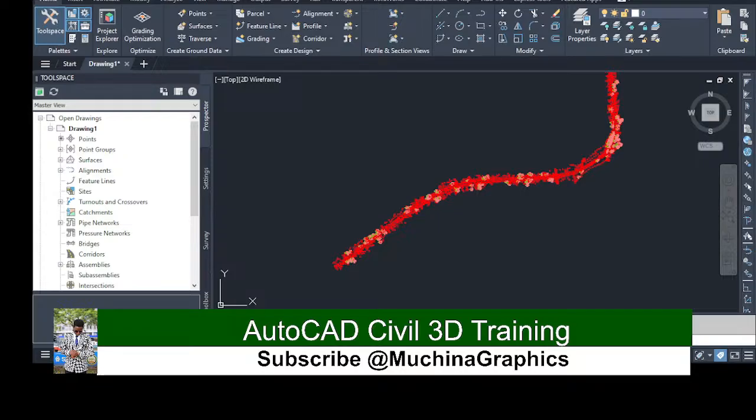So let's wait for something here to run. So I will go back to Civil 3D. So I need to create a surface. So I will click create surface. I will change name to my road surface. I will click OK. So let's go back a bit. I need to show you some setting there. I will go back to create surface.